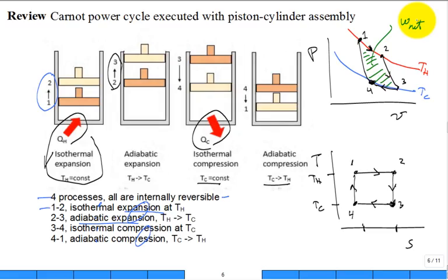Likewise, what is this shaded area on a temperature entropy diagram? Energy by heat transfer. That's right. Energy transfer by heat transfer, Q net for the cycle. If it's clockwise, it's Q net in. If it's counterclockwise, it's not a power cycle. It's a refrigeration or heat pump cycle, and you'll have to put the net Q as out, not into the cycle.